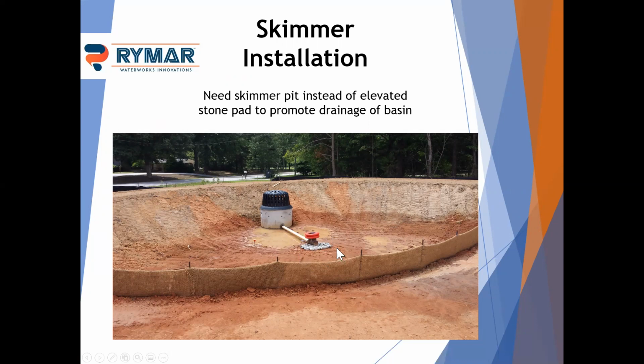Now, if this basin is supposed to be a dry basin, you're going to have a hard time getting grass established on the bottom because it's going to stay wet most of the time. A lot of times we recommend that this, we call it a skimmer pit, be graded down a little bit, and that the stone be basically at grade level to minimize that permanent volume.